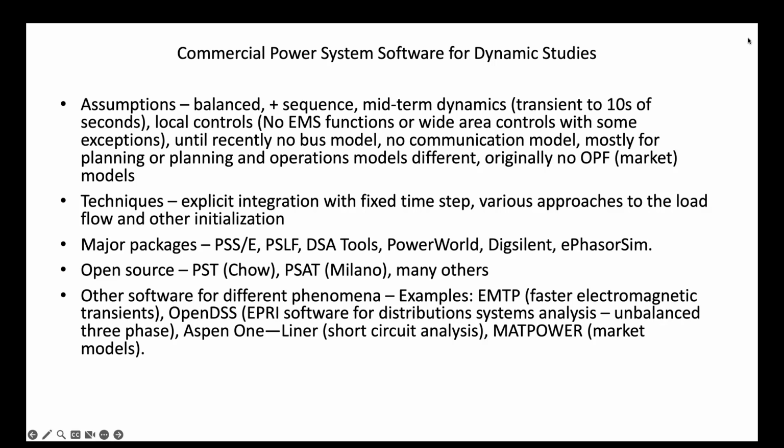Quick question. You mentioned that in planning you might just use the bus node model, and in operations you want a more detailed model. What's that one called? It's the bus breaker model. So you get the substation layout. A standard substation has several feeders coming out of it.